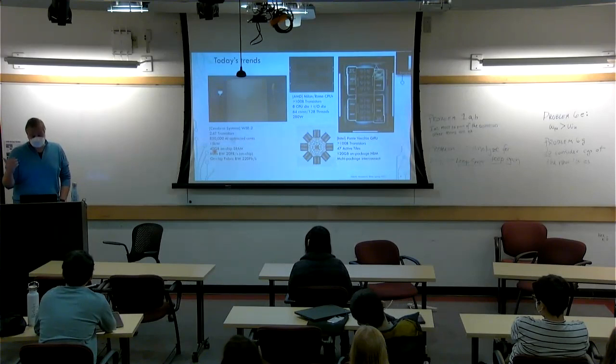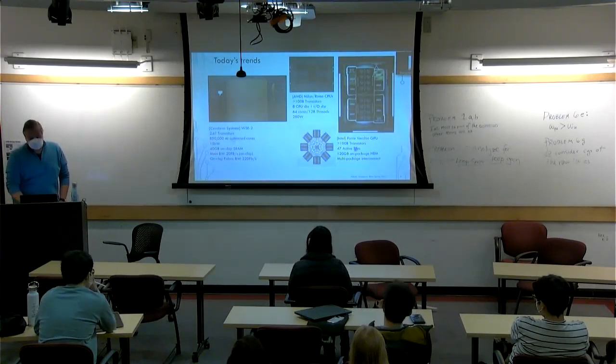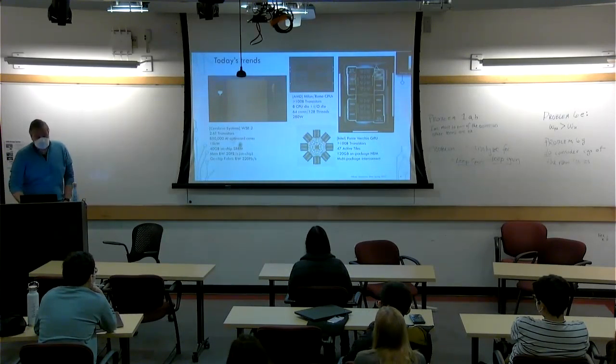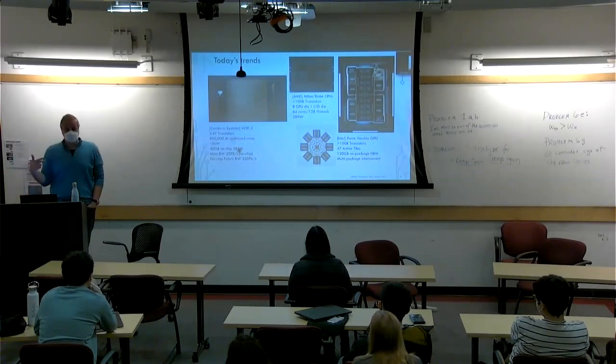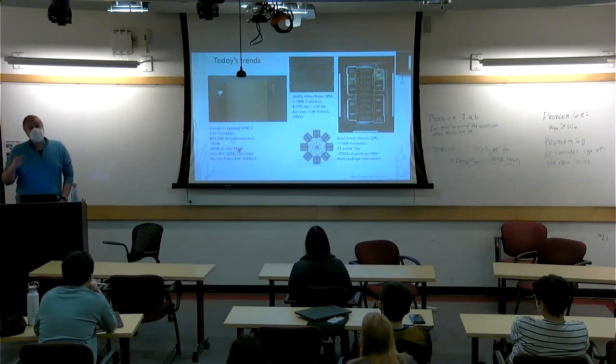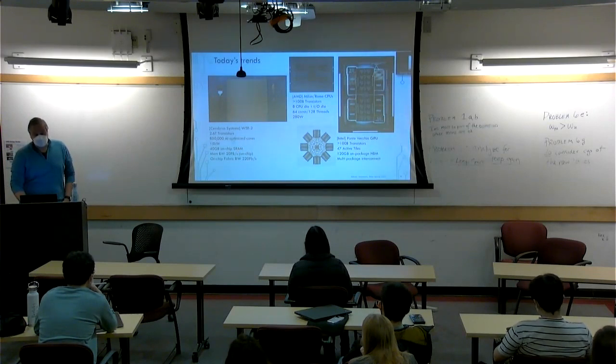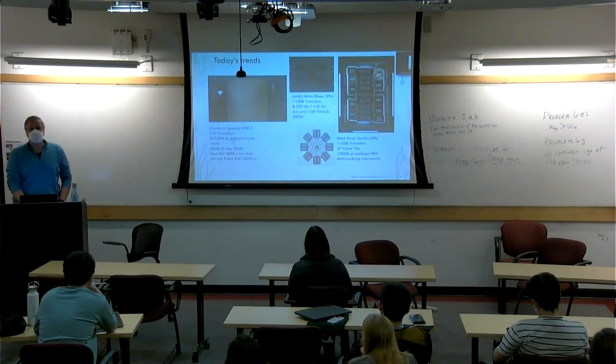Just to give you an idea, we'll show you later, the next generation Intel GPU is 120 gigabytes on these 8 HBM stacks, right? So it's kind of comparable, but this is DRAM, this is SRAM, this is super fast. This is like a clock cycle to access, right? Well, it's a clock cycle to access a local AI core. Still, it takes quite a while, given the type of network they have, to go from this core to this core's SRAM, right?